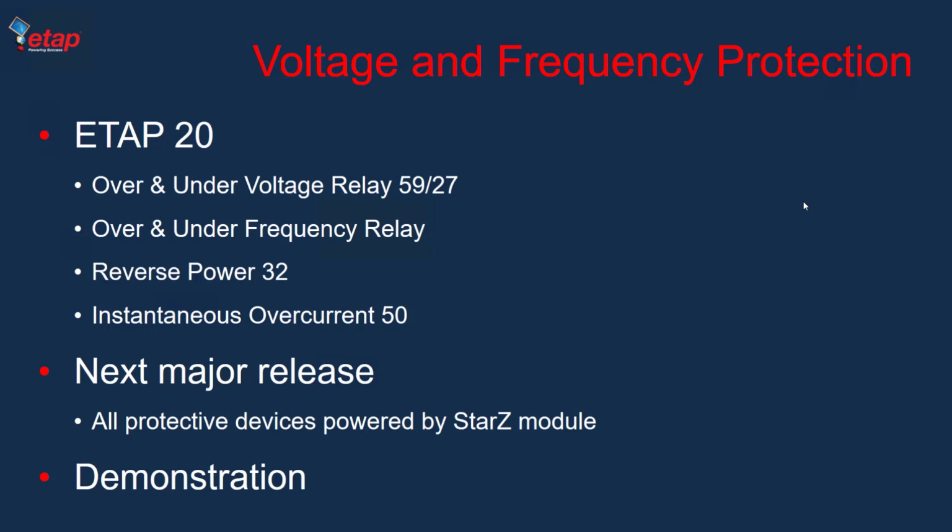So at that stage, sometimes it's needed to perform some studies, and at the same time, the grid codes are mandating all the DERs to behave in a certain way in terms of how much active and reactive power they inject during the fault and voltage drops or increases, and how long they stay in the system.